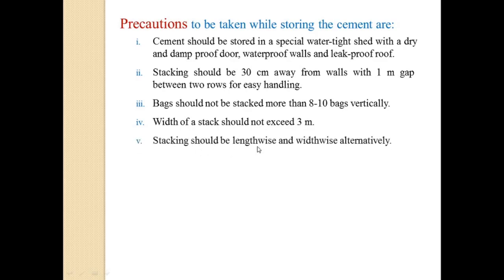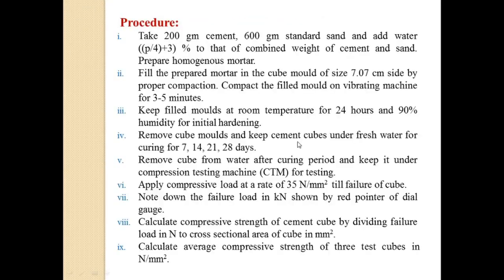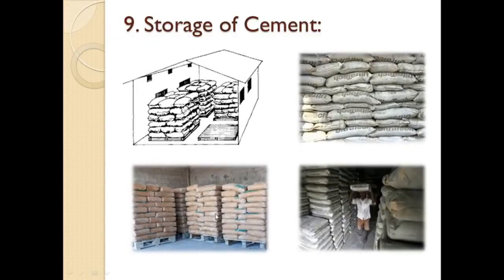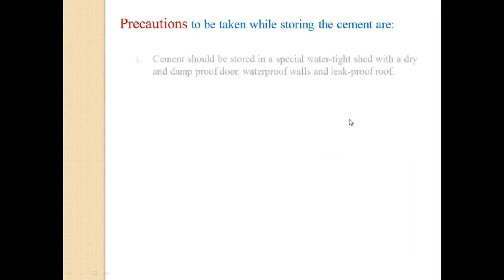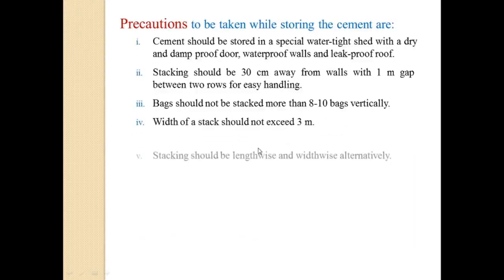Then stacking should be done lengthwise and widthwise alternately. Here we can see this stack, where cement bags are stored lengthwise and widthwise. One row we are putting lengthwise and the other widthwise. So alternately we have to store it.